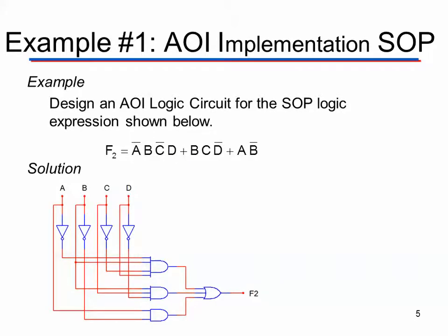Here it is implemented with 4 input and 3 input gates. You'll see that we've taken out the switch part, but in Multisim there will be a switch at A, B, C, and D. And if you follow the lines, you'll see that the first AND gate is indeed A naught B C naught D. We just attached the appropriate input lines to the gates. This schematic will fully implement the circuit expressed in this logic expression.